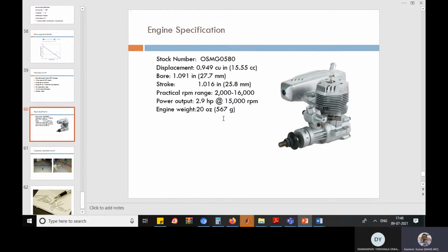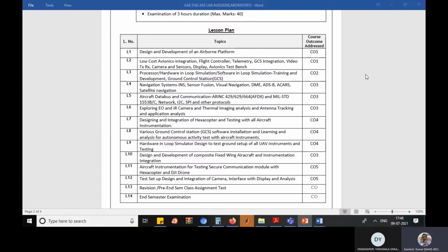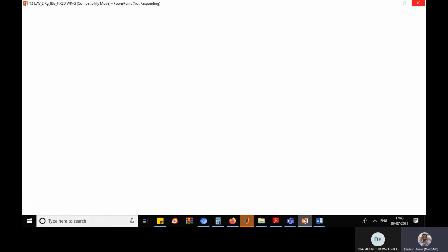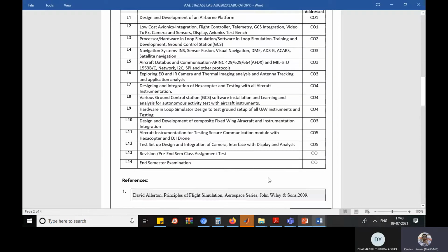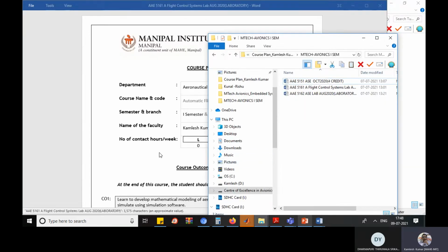So we are talking about the weight of the engine. Engine weight will be very high in comparison to a motor, but when you compare with the battery, battery weight will be very high in comparison to the engine. So you should justify what your need is. Is the need long endurance, where you get support from the engine only, or do you have an electric motor where your support comes from the battery only?